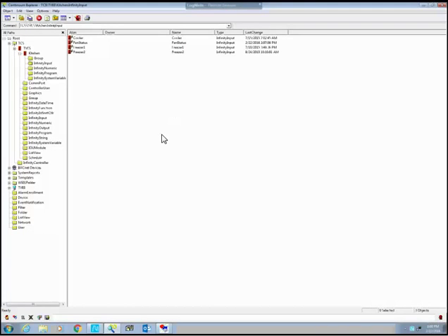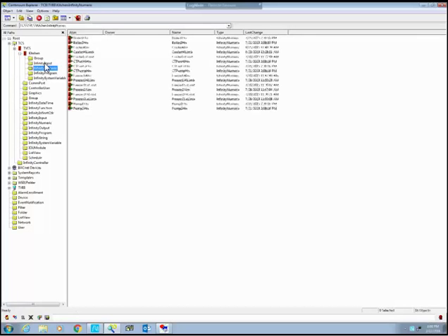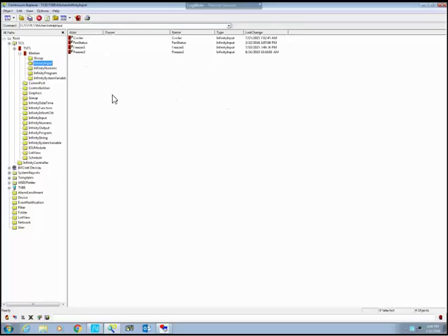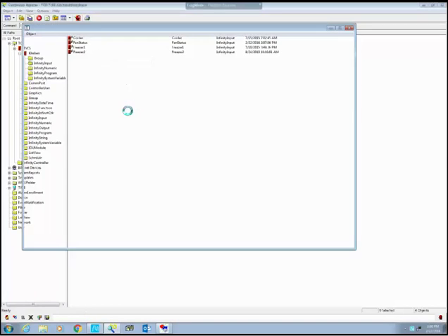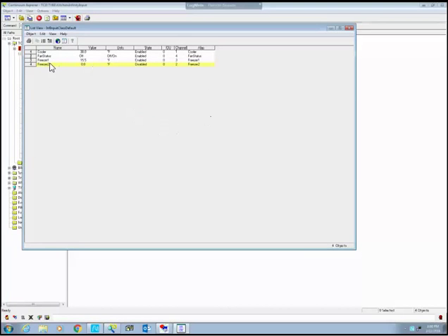Now once you save it, it'll come up and it'll be in your list of inputs for that controller. If you do a view of those, here you are. You now have 1, 2, 3, 4 inputs on there. Now you can see that's off because there's nothing on this point that's going to turn it on or off, so I can't really physically do anything to it. But if the contact was made, if it were shorted together, the value of that fan status would come on.